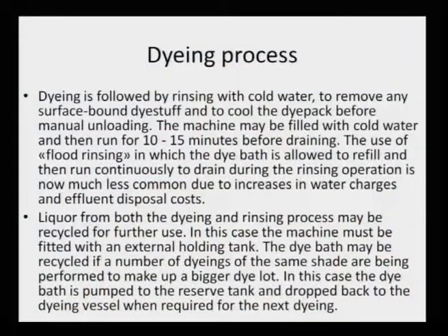So, that is what it means, that one has to take care of these dyeing processes very carefully, and in bringing it to dyeing temperature, a slow rise in the temperature helps. Dyeing is then followed by rinsing with cold water, and this is done for 10 to 15 minutes. This is a common practice because all the superfluous dye must be washed off, and rinsing is the best way to run off all the excess color.